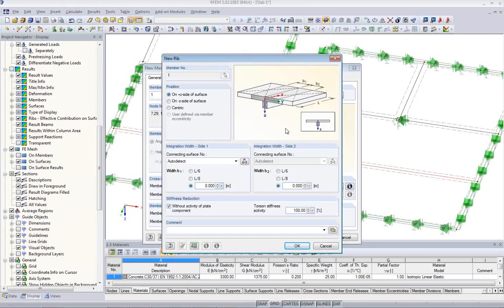and at the end I will get internal forces from this beam composed of the part of the surface and the beam itself, the rectangle cross section below. And I have to specify the effective width of the part of the surface, and I can do this here with the effective width on both sides.